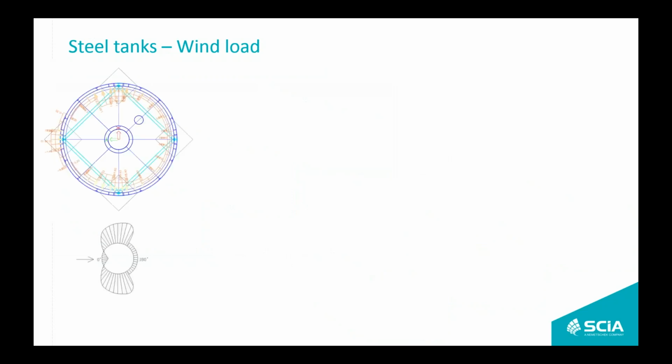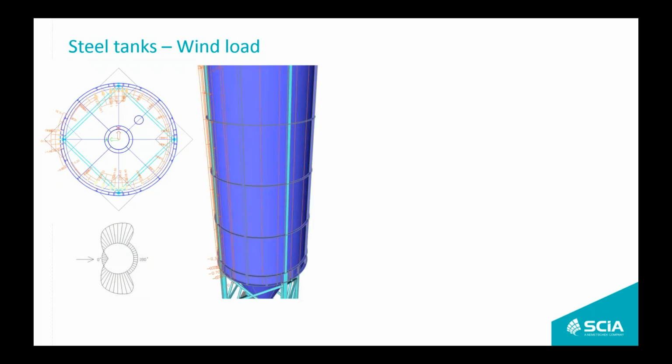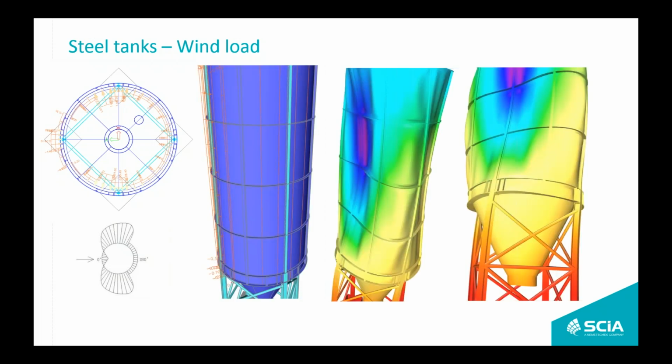What is specific in terms of wind load on cylindrical shells? In the Eurocode approach, it has both varying magnitude based on the height of the structure and based on the angle of the structural element compared to the angle of the acting wind. These actions have a big influence on the structure, and I will show you how to quickly get to results such as these.